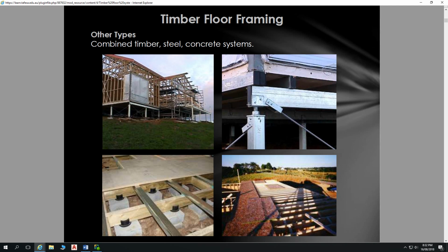That's quite important for reactive sites, because it's also just really handy for on-site assembly as well. You notice there's Tech screws fixing everything here. So Tech screws for our bracing, Tech screws to fix our adjustable top, and Tech screws for that. So incredibly quick to put together on site, it goes together very quick.